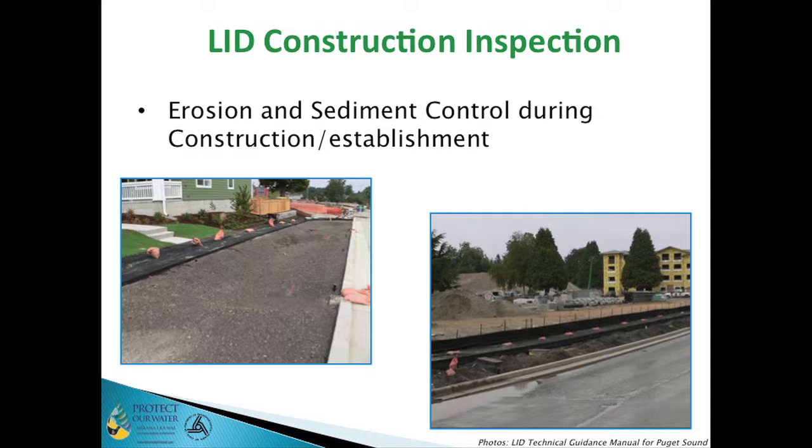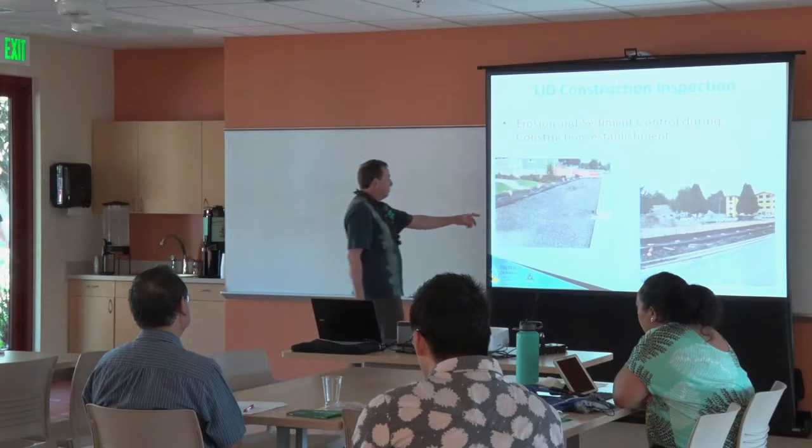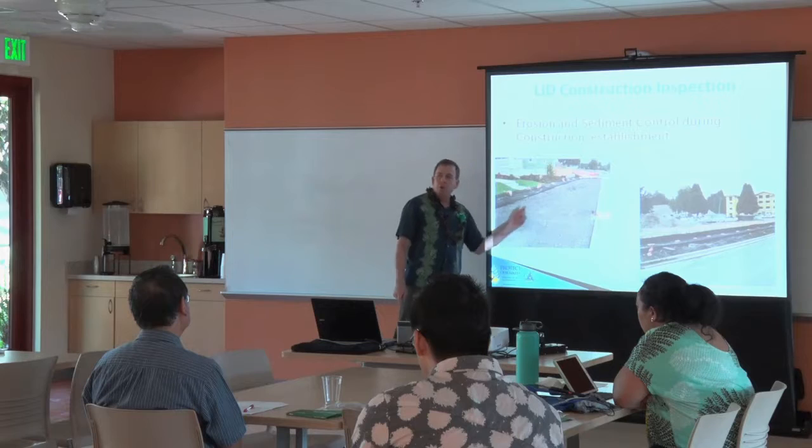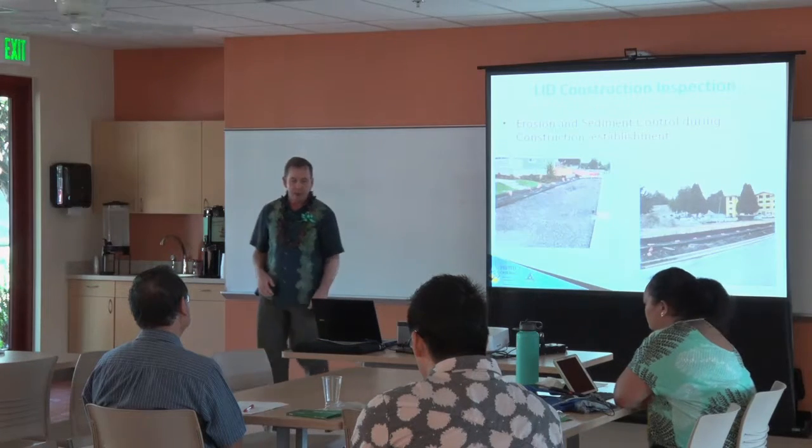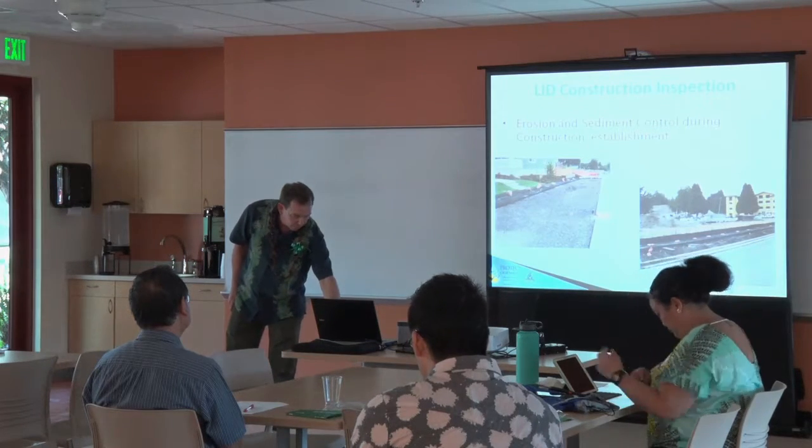And then at the end of the project, we'll convert it from a sediment trap to a stormwater pond. But we try not to do that here, because again, it's not just the volume of this depression that we're looking to save, but it's the permeability of this soil under here to let that water continue to go down. So we want to protect it during construction.